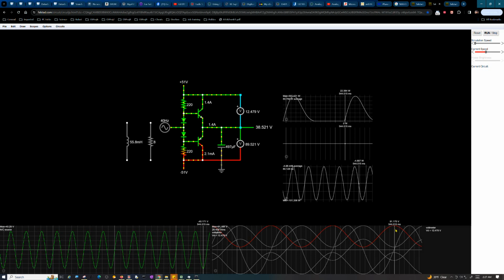Because what that guy said, he said that you get maximum current, which is this yellow trace here, right? That's the maximum current going through our wire right there. Alright, so it peaks at about 5 amps. And again, I tried tuning things to his figures as much as I could, with the frequency being different and the fact that you can't actually drive the output signal to the rail like he suggests. I had to use 51 volts instead of 40 like he talked about in his article.